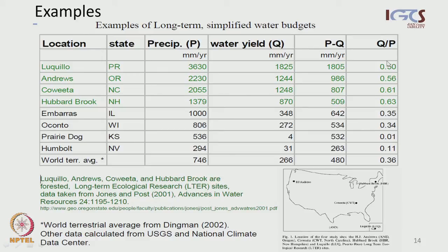This ratio is or can be characteristic for a river basin, for climate, specific climate conditions, for specific geographical regions, geological conditions, and for that reason can give a very quick first overview of what the water budget situation is over a large area, like a country.